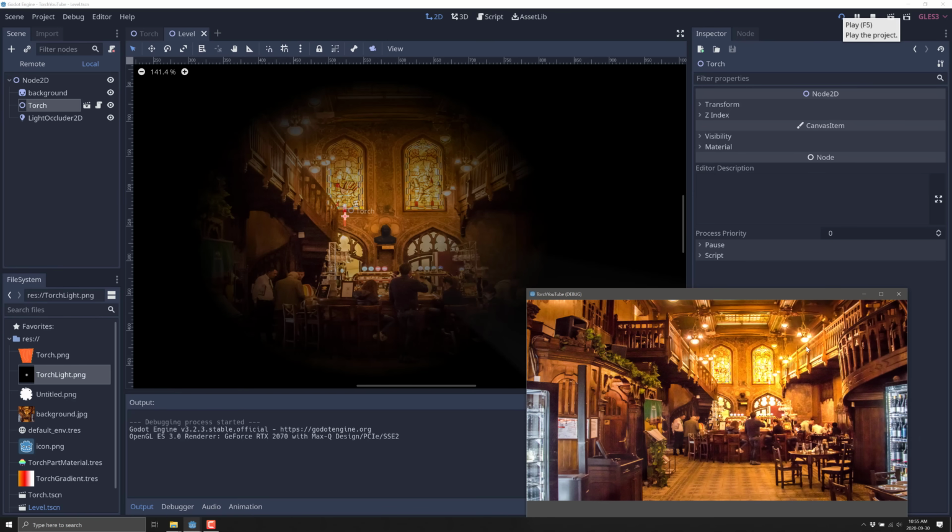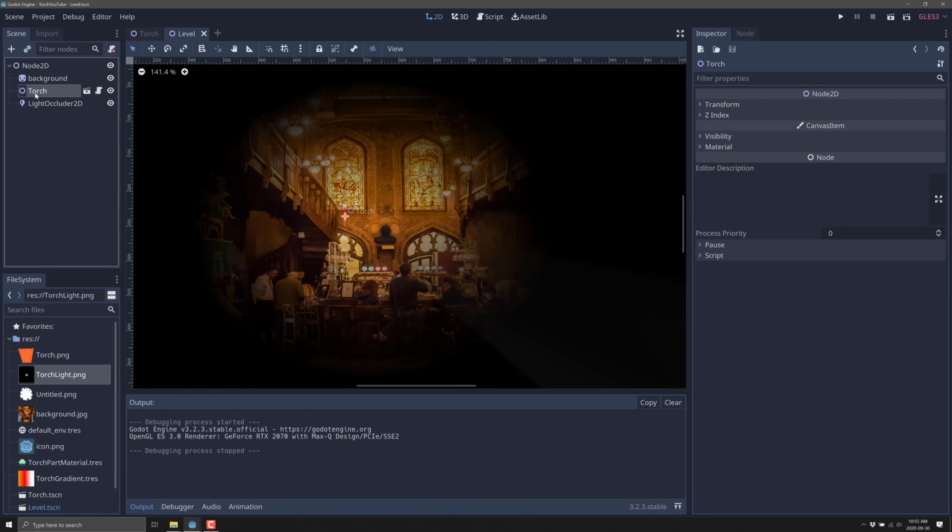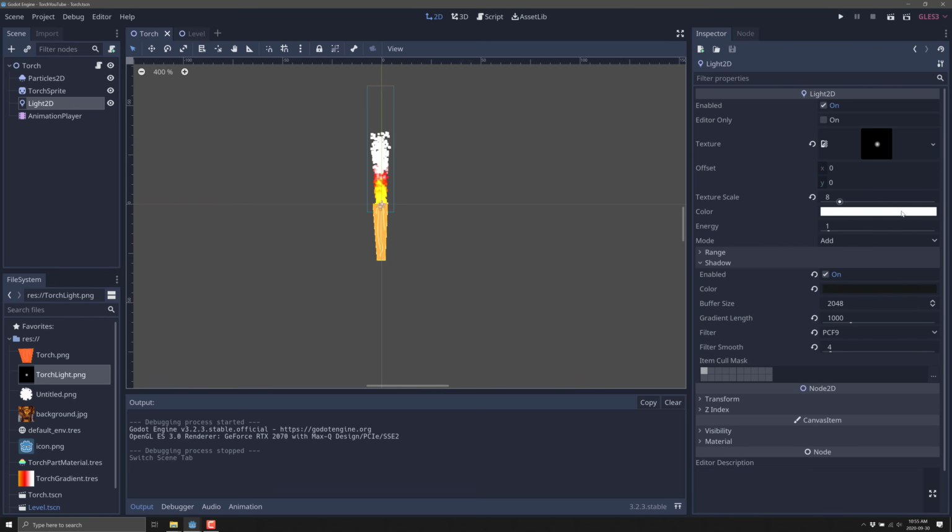So what I've done here is taken a typical graphic look and reversed it. So I've got a fully lit scene and I made it dark. But you could go the opposite approach and have it so that what happens with your 2D lights is you're adding light to the scene, not taking it away. And that would then instead involve, where do we go? Back here. Setting this to additive mode instead of masking mode. So that's just a completely different approach. You're going to flip things on your head. And if you're going to do that, what you probably want to do is actually invert this guy so that it's dark in the middle and white on the outside. And then again, you're trying to configure it so that your scene has light added to it as opposed to masking, where I'm essentially taking the light away from the scene.